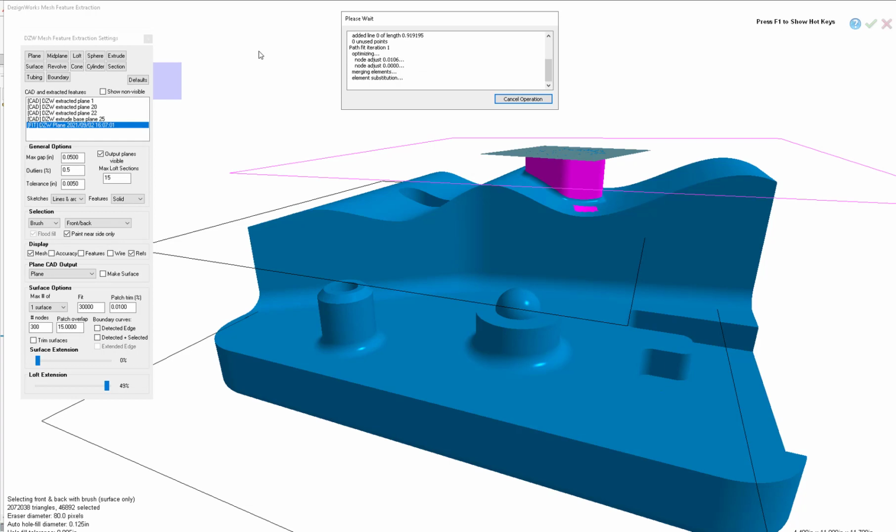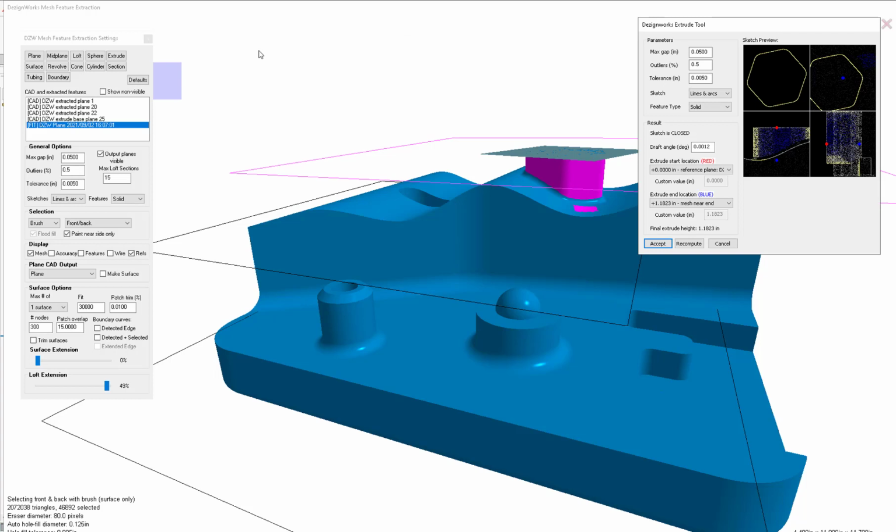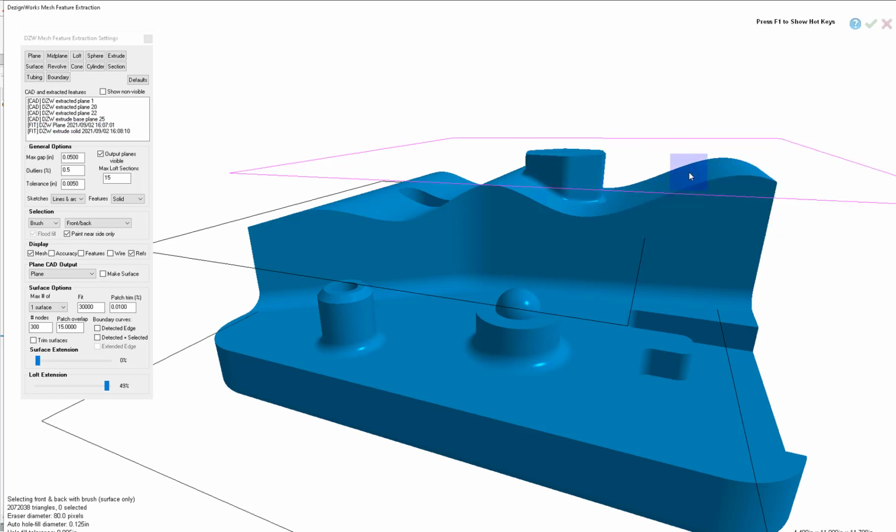So now this extrude will be down into the lofted surface. This is what none of the other products do. They all stop short. Then you have to go ahead and edit it in the tree and things like that. We're just going to say accept. Turn our feature on, and we'll build it.